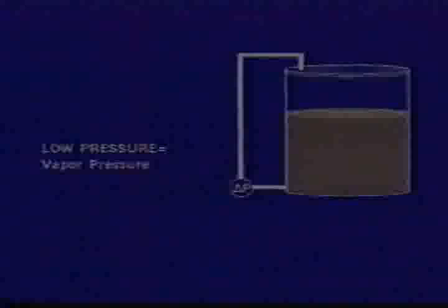The reference leg can be either completely dry or completely filled with liquid. Let's look at how differential pressure is used with a dry reference leg first. In the system, the dry leg should be connected to the low-pressure port of the transmitter. The low-pressure port receives the pressure of the vapor space. The high side also receives vapor pressure in addition to the pressure from the liquid.